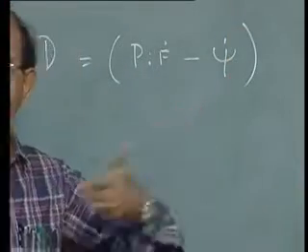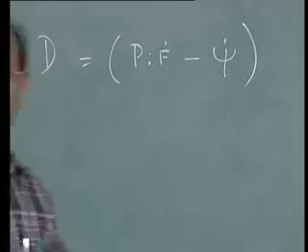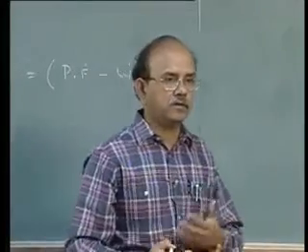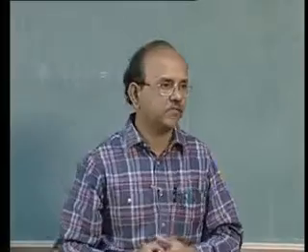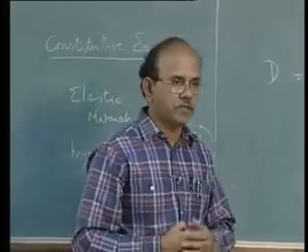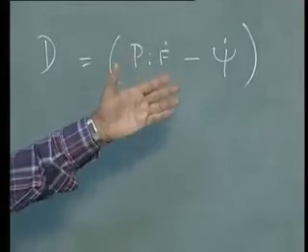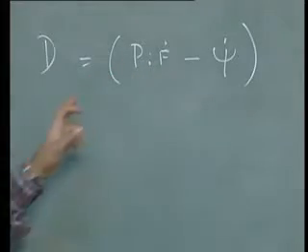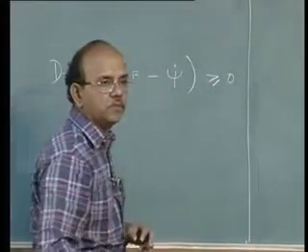What is this psi which we had introduced? Helmholtz free energy, but usually this free energy is called strain energy. The terminology most of the time is strain energy itself. Strictly speaking, what we had introduced is a free energy at that place. And if I remove all the thermal terms from it, then you would see that this term should be greater than or equal to 0.